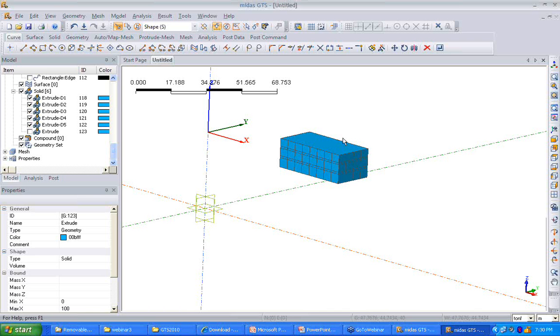But using the auto mesher, with the help of which you create 4 nodal or 8 nodal, if you go for higher order meshing, tetra solid elements, in that case you always start from in to out. You mesh the smaller elements first, and the auto mesher automatically adjusts the nodal connectivity and the size of remaining elements as you move from in to out. But if you do the vice versa, moving from out to in, there can be a problem with the meshing, because the required size of tetrahedral element might not be created.